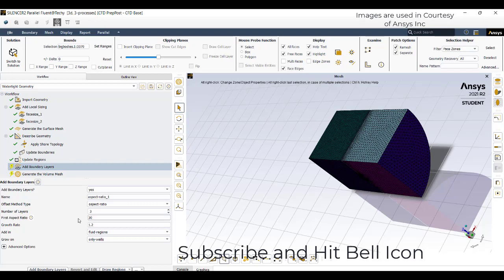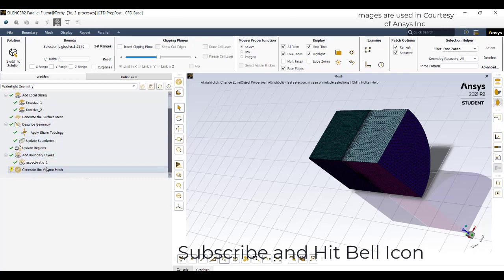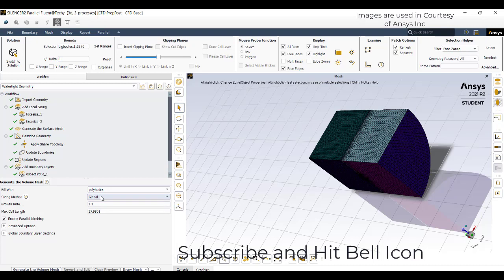Right? So for high turbulent flows, you need to have a very less boundary layer thickness. So I'll be selecting 30. It's for the reference purpose. Add boundary layers. So after that, go to generate volume mesh. So I want to generate volume mesh.